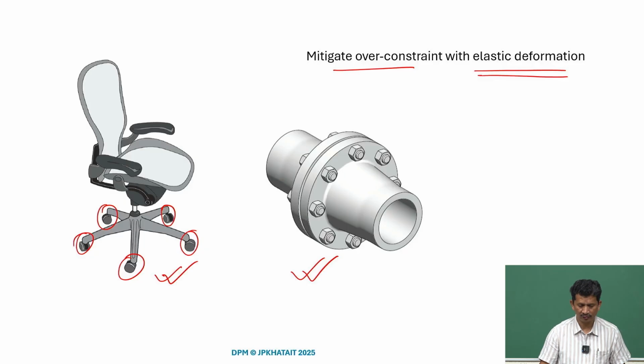What we also rely on in this case is the clearances of the bolts. The main purpose of using bolts is to create the joint, and sometimes we use them even to locate, but as we know, location using bolts may not be a good idea because the clearances are there, and we have to use some kind of jigs and fixturing to get a proper alignment.